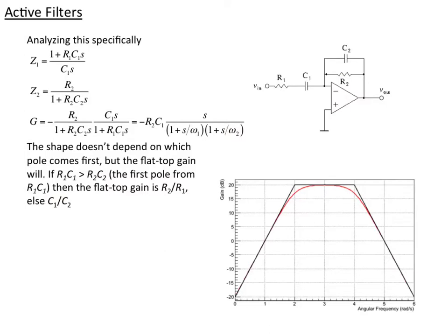And so when we look at this, then we can plot it using our Bode plot methods, and we notice there's a root at 0, so we expect this rising line. And then we have two downward shifts at omega 1 and omega 2, and here I've put them at 100 and 10,000. This is the log of the angular frequency plotted here. And the gain in decibels here. So we go up, we turn, we go flat, we turn, we go down. 20 decibels per decade going up, 20 decibels per decade going down. We have a flat top.